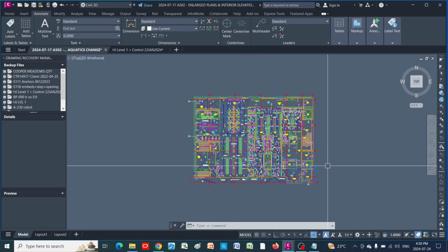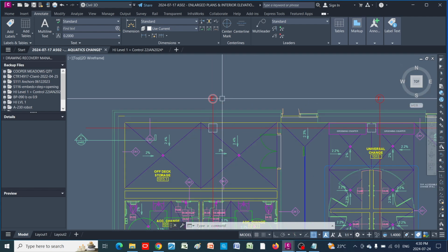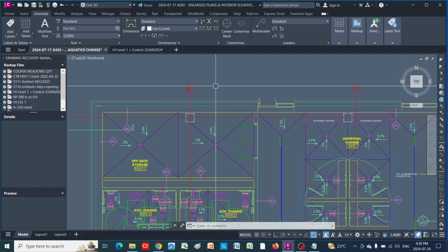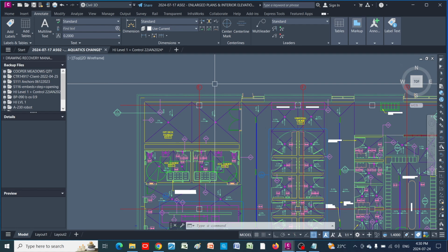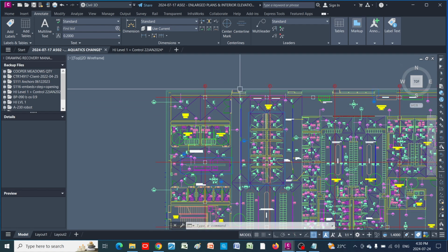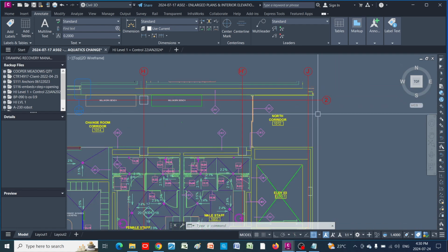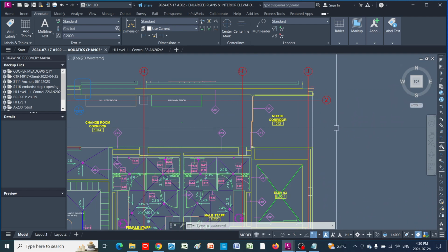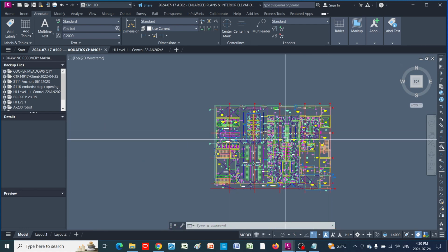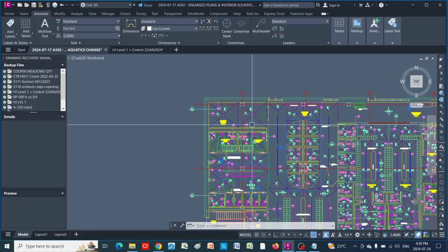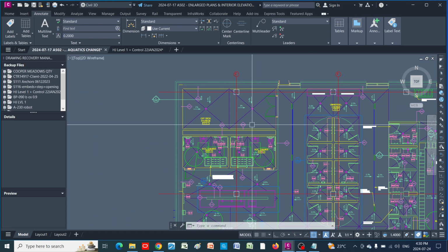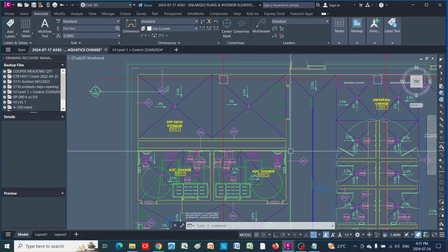So we have grid lines here. These are put by the architect on a strategic part of the project. They are composed of vertical and horizontal lines, right? So we do layout by measuring distances from the grid lines. For example, I'm gonna lay out this wall at the job site.